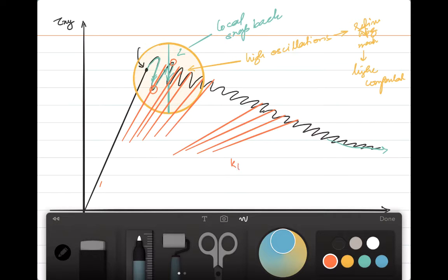So the KT, the tangent stiffness slope, is reducing gradually as the analysis moves forward. And this is the effect of material softening. So what we are doing here is that we are able to reduce the stiffness of your material by taking into account the traction separation law that we looked at before.